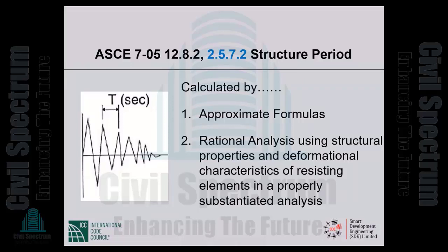Okay. So in the design base shear equations, we have the period T, we have R, we have I. So we have to discuss all of that. The period is a function, remember, of the mass and the stiffness. To start with, before we have designed our building, we do not know the mass and the stiffness. So we cannot calculate period. And without period, we cannot calculate the seismic forces. So it is the classic chicken and the egg situation. Which comes first? So that being the case, our codes give us approximate period with which to begin the process.